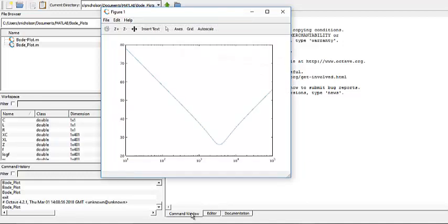it generates that graph. Okay, and it's kind of like the graph that we looked at using LTspice, except it's probably a larger frequency range. And what you find is that the minimum impedance occurs at a frequency of around, this is 1,000, this is 2,000, 3,000, so it's about 3,500 hertz.